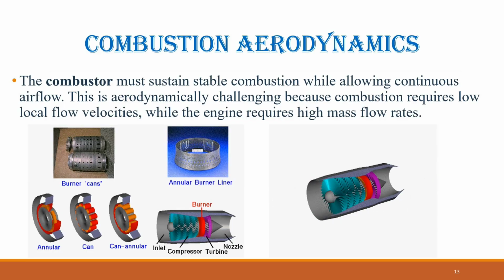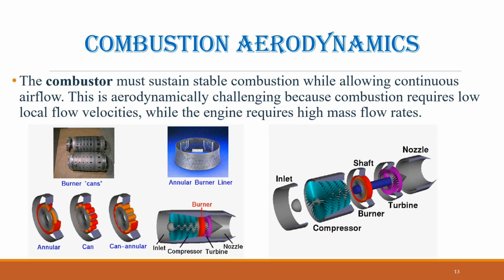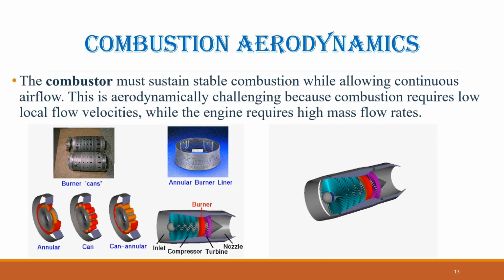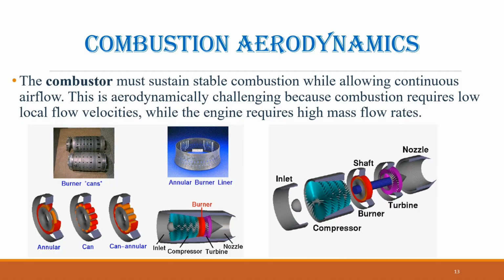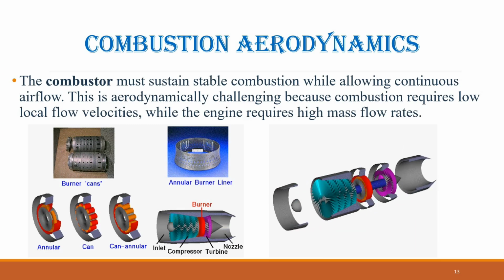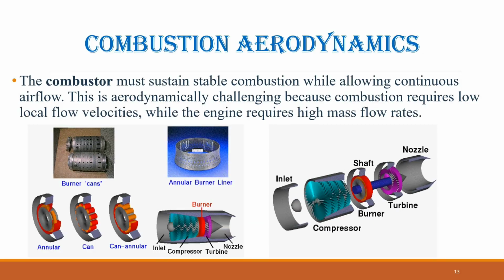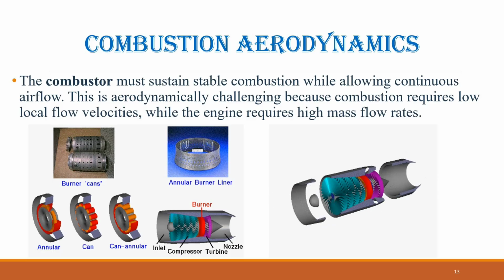Only a portion of the air entering the combustor participates directly in combustion. The remainder is used to cool the combustor walls and dilute the hot gases before they enter the turbine. In engines such as the CFM56 or LEAP, advanced fuel injectors and swirlers are used to ensure uniform mixing and stable flames. Modern combustors are also designed to reduce nitrogen oxide emissions by controlling temperature peaks, as seen in the low emissions combustors used on the Boeing 787.